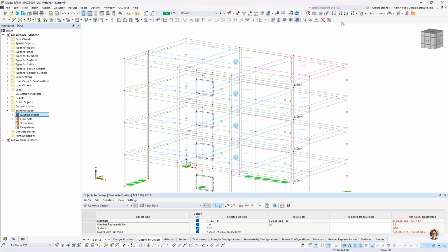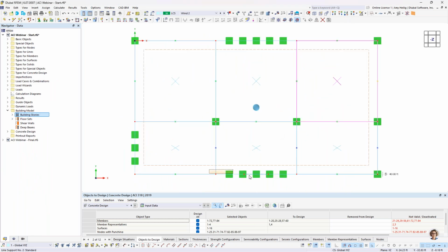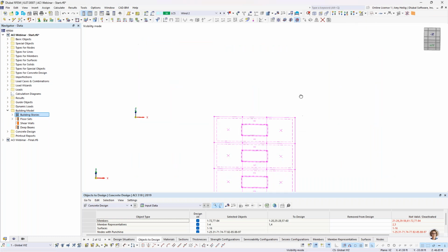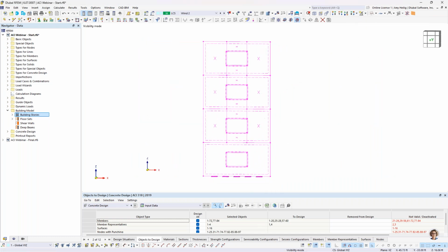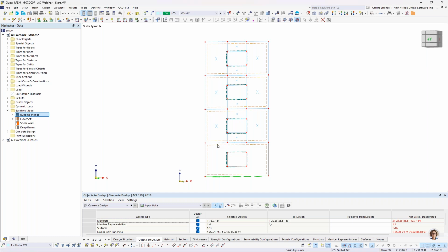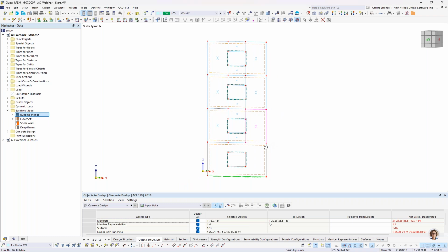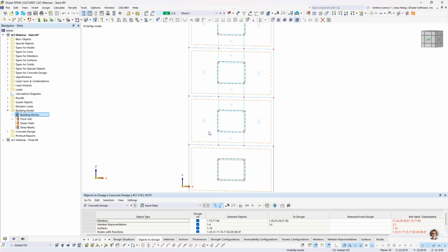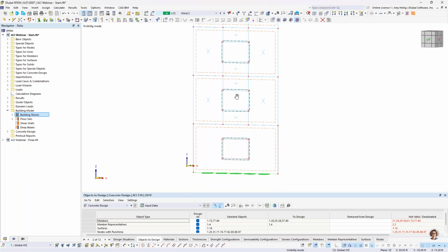And you can see here that it creates these surface cells at various portions of the structure on the surface elements themselves. Well, I'm going to turn this into an elevation view here, and I'll go ahead and highlight only my front shear wall. So here we have our 4 shear walls displayed graphically, and you'll notice that those surface cells for the shear walls at the 2nd, 3rd, and 4th level are shown. And this is really helpful because this will help us define what is a shear wall on the left and right hand side versus what's a deep beam that's spanning in between these openings.